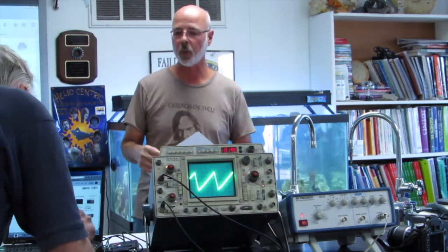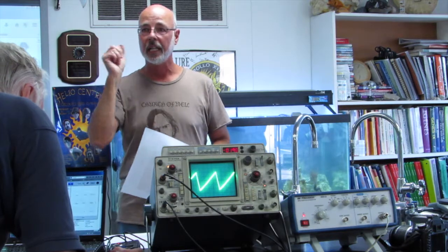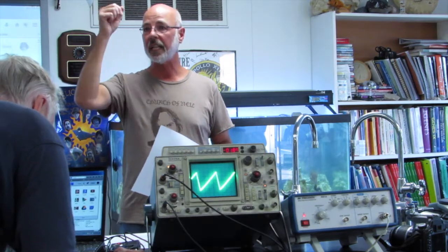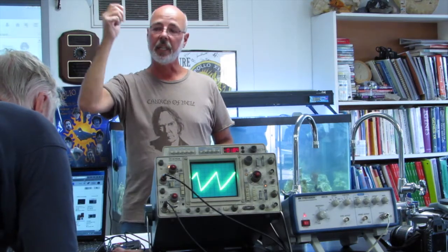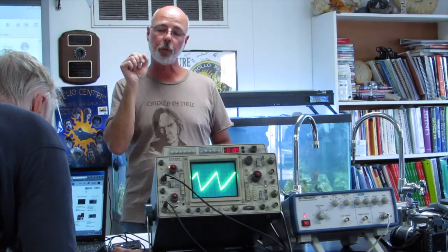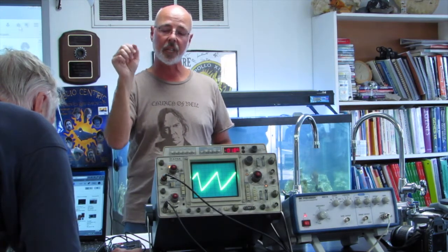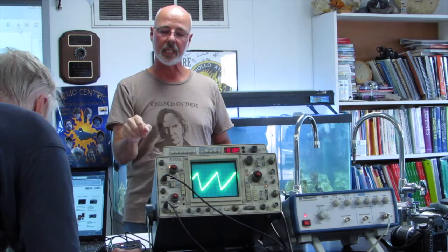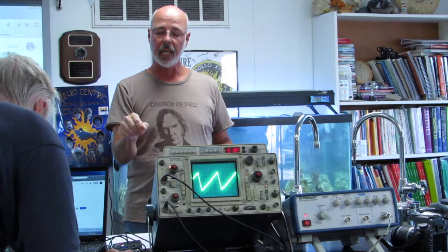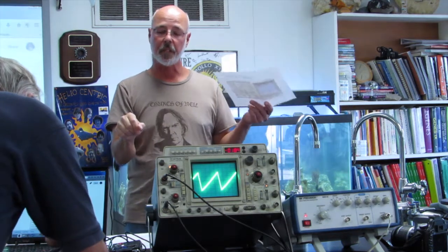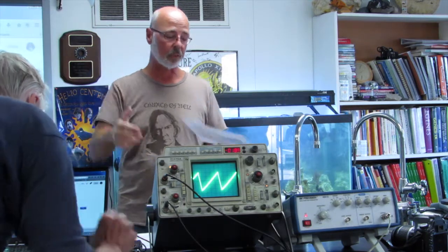So you can see, like a flashing LED, for example, on an Arduino circuit, one side of the LED will be tied to some voltage, like 3 volts. The other side will be connected to the processor, and if the LED is flashing and the LED is on, if you were to probe it, you would see that the other end of that LED was probably at ground, 0 volts. And when the LED shut off, you would probably see that voltage go up to 3.3 volts, and there wouldn't be any voltage across the LED at all.